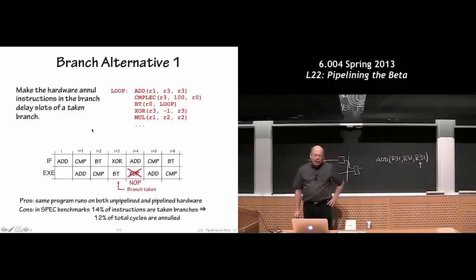When I take the branch, what I'm going to do is simply replace that XOR as it moves from the instruction fetch. So I sort of know the branch decision right here. As this instruction would have normally moved through into the instruction register for the execute stage, as it does that move, if I don't want to do it, I'll replace the instruction I fetched with one of these magic no-op instructions. Okay. So you can say, well, that gets the job done.